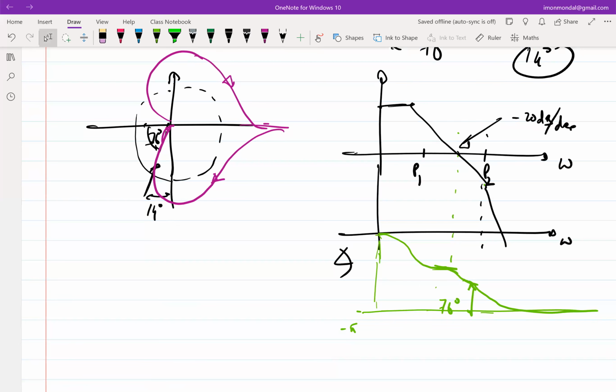So the hack that circuit designers often use to understand if a system is usable or not is to find out the slope of the Bode plot around omega U loop. If the slope of the Bode plot around omega U loop is minus 20 dB per decade, or looks like a first order system, most probably it is also stable, right? Stability is a huge branch of mathematics. It comes from complex algebra, complex analysis, complex calculus, lots of theorems broken down into one statement: does your system look like a first order system around UGB?